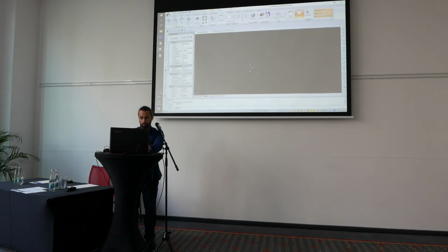We just used the usual polyline command as an example, so we derived all submenus or options from it. We can set distance before entering the next point.